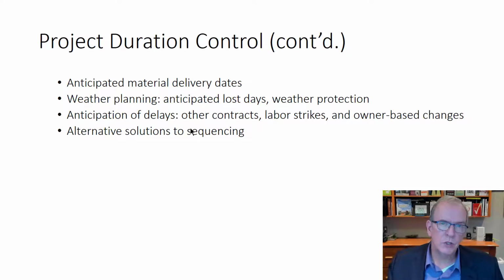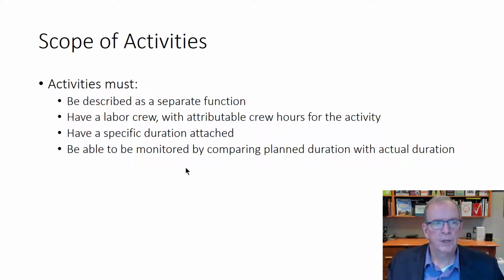There are certain things we can't change, right? If we're talking about constraints with our resources, there are certain technical constraints. Can't put on the roof membrane unless the roof substrate is on first. Certain things have to go a certain way, but there are other things we have a little bit of flexibility with. So we need to have clarity on the activities. We need to assign the resources to the activities and figure out what's the combination and what productivity rate they will achieve. And that will help us define the duration for the work that's going to be done.